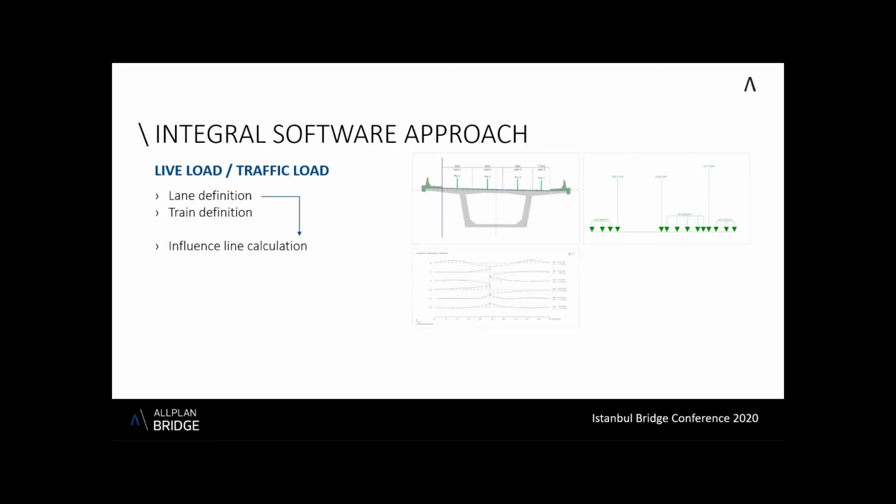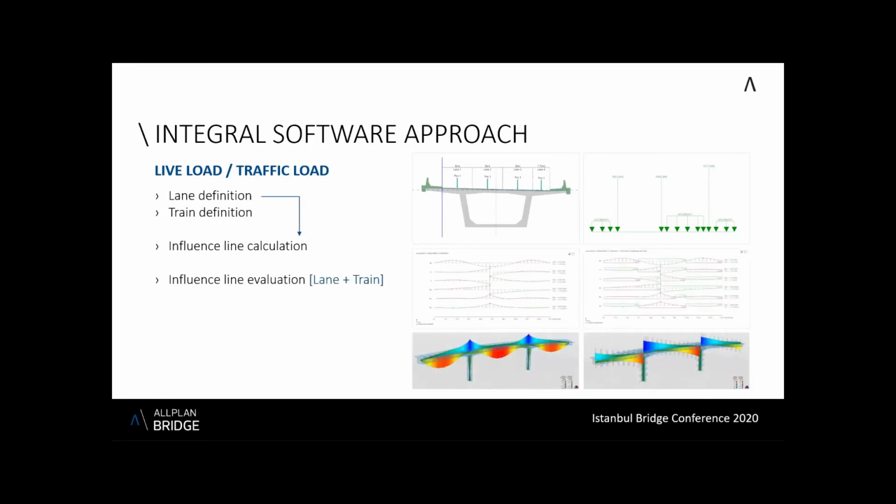Notional lanes along the bridge surface are defined in the bridge model in addition to the actual geometry data of the structure. Several constraints must be considered with respect to the arrangement of these lanes on the bridge. So different possible lane sets must be defined and different lanes must be loaded with different traffic load intensities.